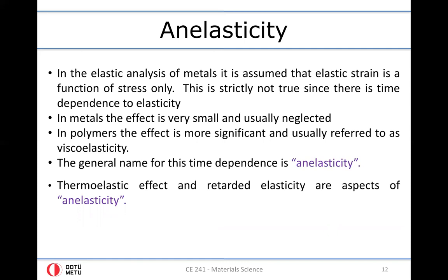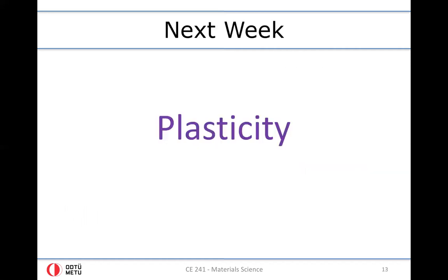That is going to be the topic of the chapter that we will cover in week number 9, I believe. So in general, this kind of time dependence, the time dependent deviations from the elastic response, is referred to as unelasticity. And thermoelastic effect or retarded elasticity are some examples, aspects of unelasticity. So this is pretty much all I'd like to say about thermoelastic coupling.